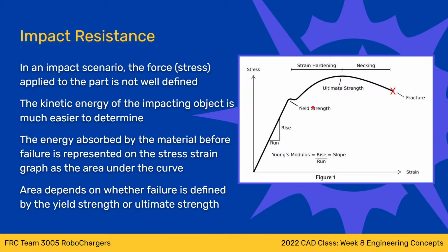And the interesting thing here is that generally the slope, if I can call it that, of this curve is quite a bit less after you exceed the yield strength. The more strain you add, you don't add stress as quickly, I should say. And so the curve kind of flattens off is basically what I'm trying to say.